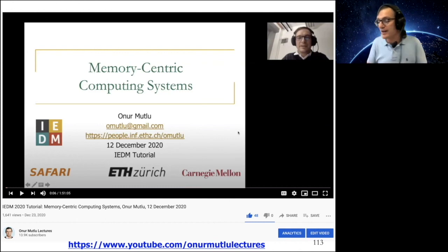The fundamental RowHammer phenomenon exists in any other memory technology, but you may not be able to launch RowHammer attacks on them because those bit flips are not immediately visible, and they are also corrected before they become visible at all, if they become visible. So these are very good questions.